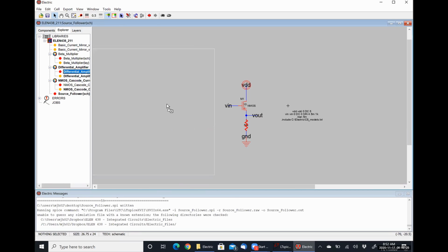So is this effectively just like a voltage divider? It's an output buffer. So what I'm trying to do here is if we hooked up, say, a resistor as the load of our differential amplifier, because that resistor would be in parallel with the output resistance of our differential pair, if that resistor is smaller than a couple of mega ohms, which is what the output of our differential pair should be, we would see that it effectively shorts our signal to ground almost.